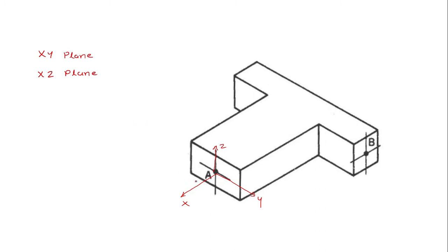Remember one thing, it depends upon how you are orienting this axis. If I take my xyz in this fashion, I have a plane of symmetry along the xy plane, and I have a symmetry along the xz plane. So this is for point A. From this I can get that x, y and z are the principal axes, if I have two principal planes as such.